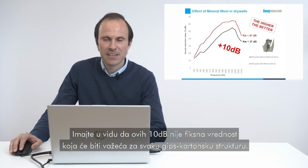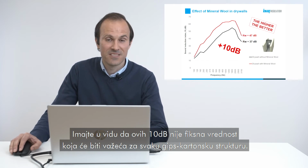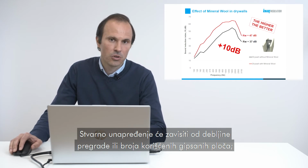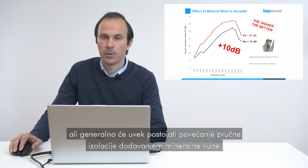But please have in mind that this 10 dB increase is not a fixed value that is valid for every single wall structure. So the actual improvement will depend on the thickness of the partition or the number of gypsum boards utilized. But generally, yes, there will always be an increase in the airborne sound insulation with adding the mineral wool.